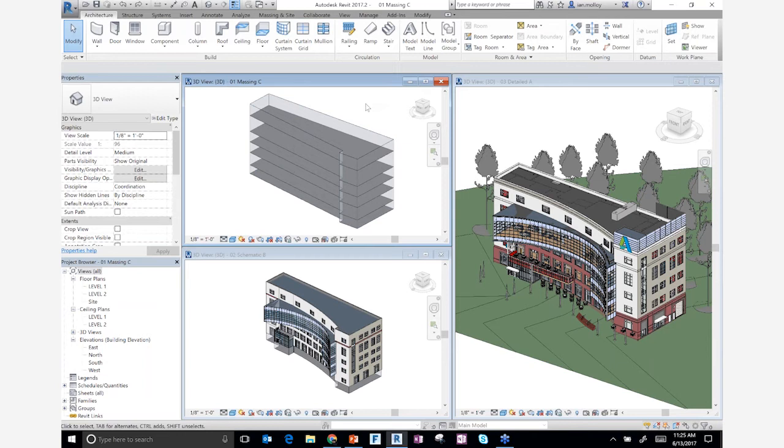So if you start with something as simple as conceptual, I'll show you how the energy model is created. But just to note, I'll show you how we can create an energy model from a detailed model. If you've never created an energy model before on a brand new project and you've got this detailed model, there's 1 or 2 things you can do. You can create a detailed energy model, which can take anything from a few minutes to maybe a couple of hours. That's opposed to days and weeks for a traditional manual energy model. You can, of course, also create a very simple representation of the building. People tend to not put a lot of value in these, but they're actually incredibly valuable because they can answer different questions about the building that this model can't.